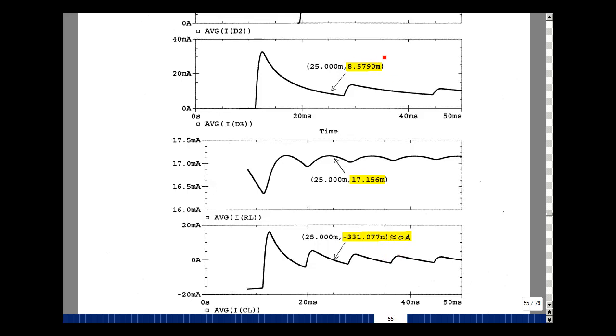We can hand calculate this with our formula, that the average diode current is 1/2 V out over R sub L. If we took 1/2, our average value is 16.95 volts. Dividing that by 1K, I get about 8.4755 milliamps. This is the exact value. Our formulas are an approximation. They get us close, but we can always verify our results.